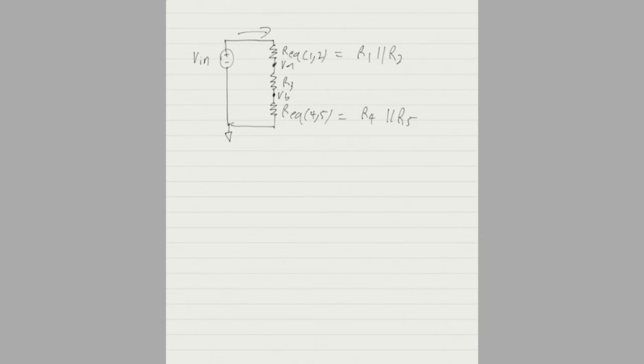Well, we just calculated the current. Since we've just calculated the current, we know that this current, by Kirchhoff's current law, is going to be going through all of these resistors, because as the current leaves the resistor, it has to enter the next one. So the current through our first equivalent resistor, our R3, and our final equivalent resistor is all the same. So the way that we're going to do this now is we have Vn is equal to VReq high plus, and that's just what I'm naming Req 1,2, just so I don't have to deal with subscripting parentheses, because that would get really messy, plus VReq low.